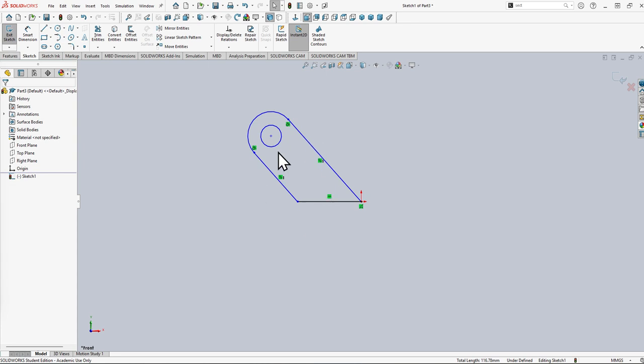Depending on what dimensions you're changing or how complex your figures can get, that could be very important to you because you don't want things moving around or getting funky. If they weren't tangent, and you were to change the dimension of this, it's going to force these lines along the way instead of it getting all weird angles or not tangent at that point.